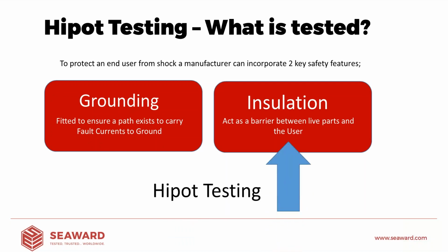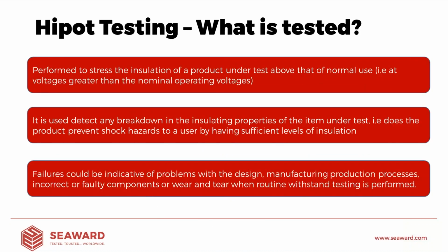And this is where the Hipot test comes into play. We're going to stress the insulation to make sure it's sound and doesn't provide a shock. So what is tested? As we said, the idea of the test is to stress the insulation of the product under test above that of normal use.